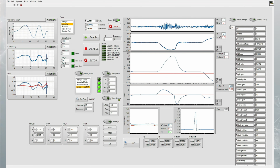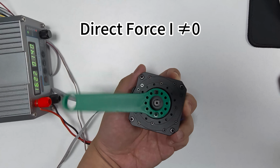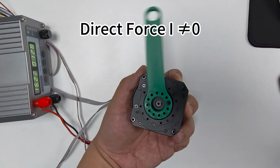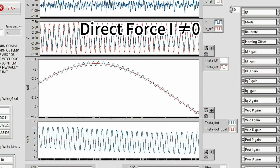Step 2. Avoid the I gain. Keep the integral, I gain, at 0. Any I gain will accumulate error, destroy the predictable spring physics, and cause oscillations or violent bouncing upon environmental impact.